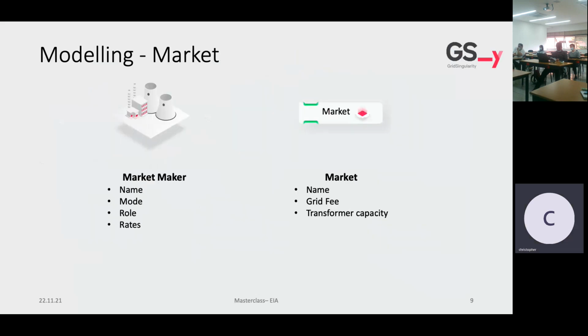We also have a market maker, which is a very important role in our software because it mimics the typical behavior of an energy utility. If you have an energy community, the market maker will sell an infinite amount of energy at a fixed price. We also implemented the infinite bus mode, so that it's possible to simulate a feed-in scheme. If your community has an energy surplus from the PVs or other producing assets, this surplus can be sold to the grid at a fixed rate.